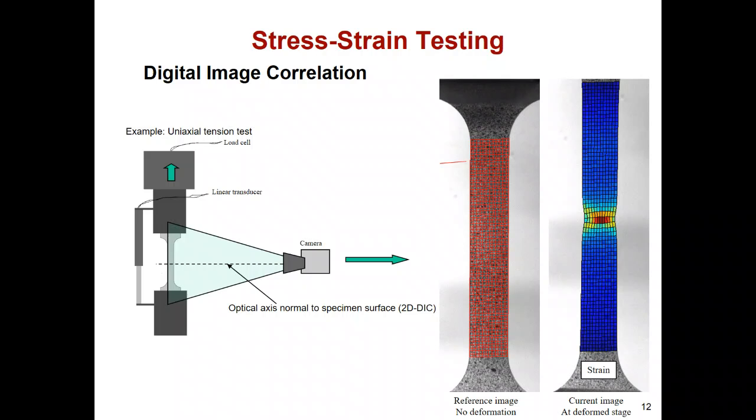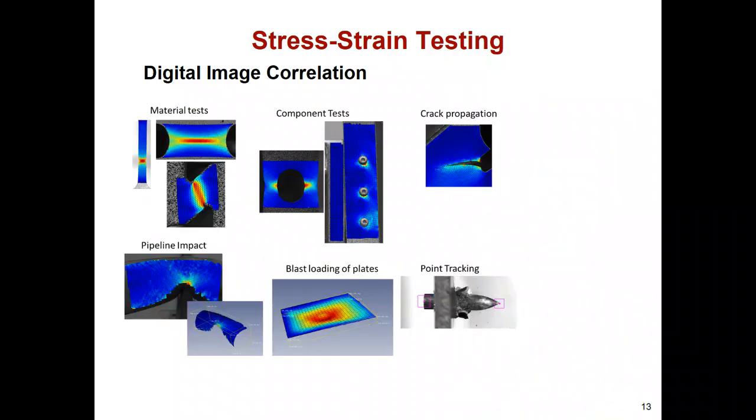But one problem is that to obtain the strain field, tracking the particle image requires several snapshots as the pattern moves from one position to another. Without very accurate images, we cannot achieve that goal. However, digital image correlation can be used on various types of solid specimens.